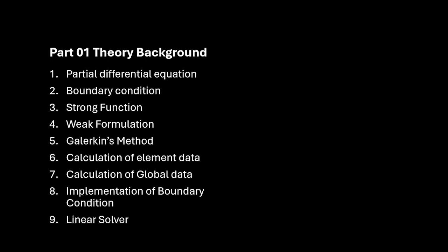My lecture will be in two parts. In the first part, I will teach you the theory and background of the finite element method. What are partial differential equations? What kind of boundary conditions are implied? What are the strong form, weak form, and Galerkin methods to get the shape functions and divide the domain? And how to calculate the element data like the element stiffness, element force vector, everything.